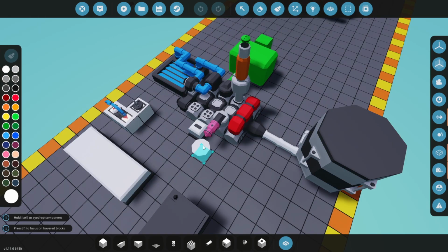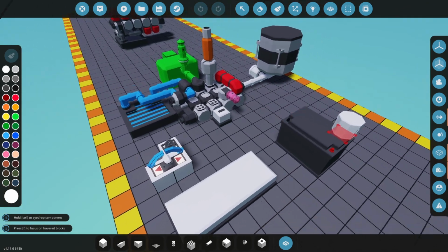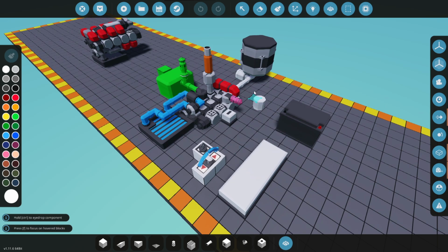With a car, say you have the wheels properly done and you need 0.5 throttle, like in this case, what happens when you stop? What happens when this clutch is reading 0? Well, what's going to happen is your engine's just going to shoot up to the RPMs and it's going to be jumping, redlining until you put load onto it. So there is a much more refined balancing act when it comes to vehicle motors and engines, but for this very crude constant throttle type of system, especially for generators, this is really all it takes.